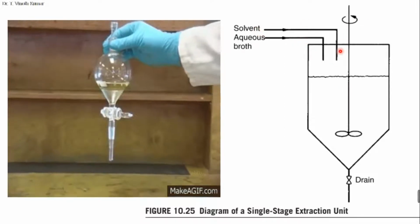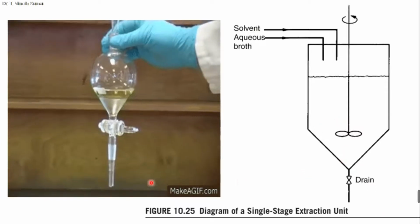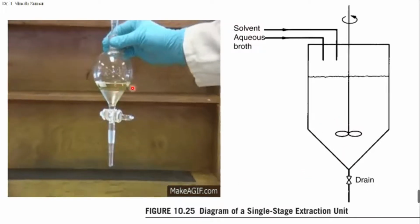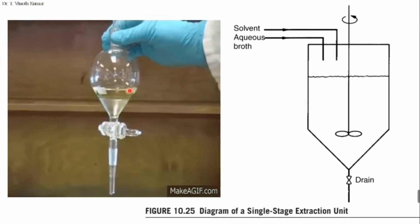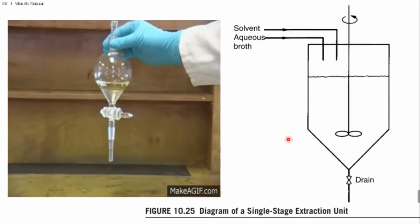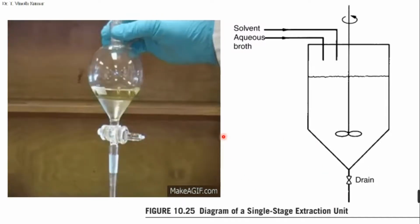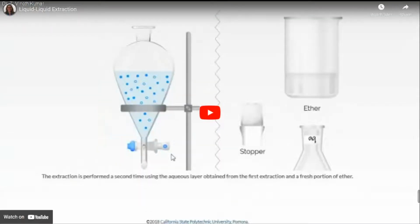So the solvent is added and the aqueous broth is added, mixing completely, and after the separation like this, there are two phases. The bottom is aqueous and the top layer is organic, and by opening the stopcock we can collect it. So this is called a single stage extraction unit, and I'll play a video explaining the complete principles of liquid extraction, just to have a look.